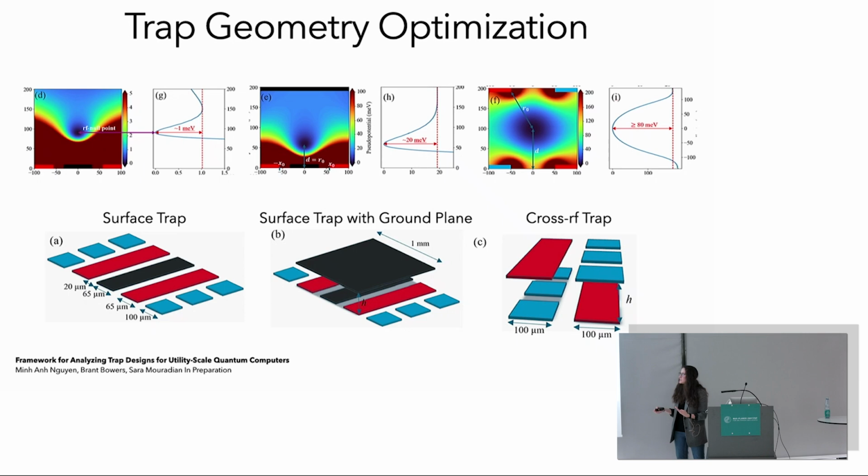For instance, with that superconducting measurement, one thing that's really difficult is that you also get electric field noise from the environment. So making sure that your qubit is limited by electric field noise from your surface is very tricky. We have some ideas about how to do this by measuring spatial correlations between two traps, because electric field noise from the surface should be uncorrelated, but electric field noise from the surroundings should be correlated. We're hoping to get a more quantitative understanding of what's coming from the surface. But so far, there have been tons of studies and no one knows. It's very unclear.